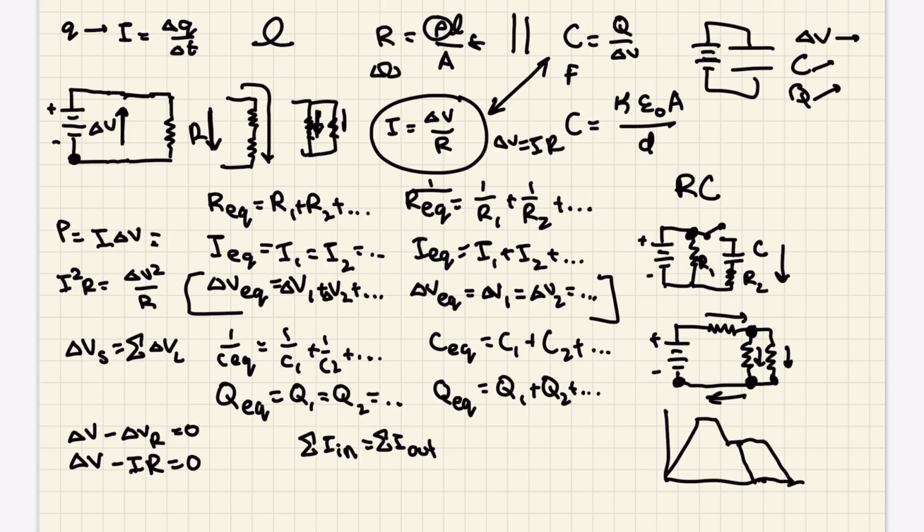Now, what do these two rules have in common? They both have to do with conservation. The first one is conservation of energy because it's talking about voltage and how it's going to end up at a voltage of zero at the end. It goes through all the voltage gains and drops and ends up at zero, which means voltage is conserved and therefore energy is conserved. Second one, conservation of charge. It basically says that current is constant in here. Basically, you cannot change the current.